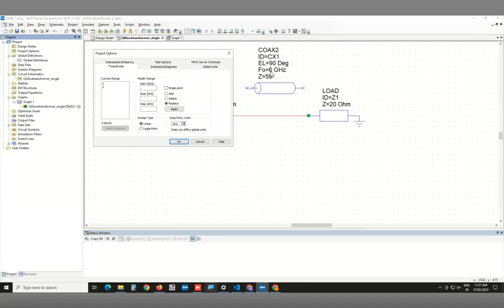This is around 6 gigahertz, because you remember an impedance transformer only does perfect matching at one particular frequency. And then it gets worse, and that sort of defines what range of frequencies one can reasonably use this as a good impedance transformer. And that's related to one of the options in the question. So we are working around 6.